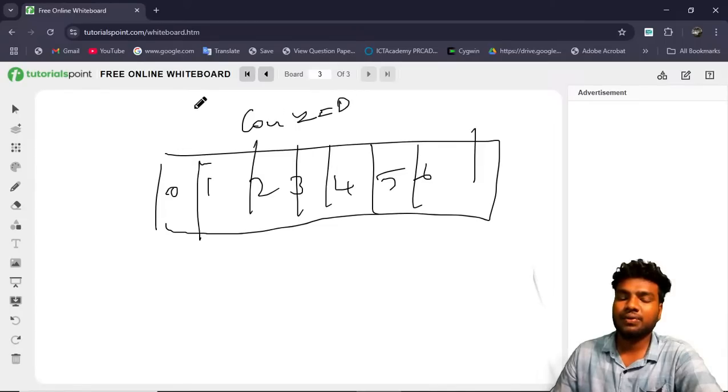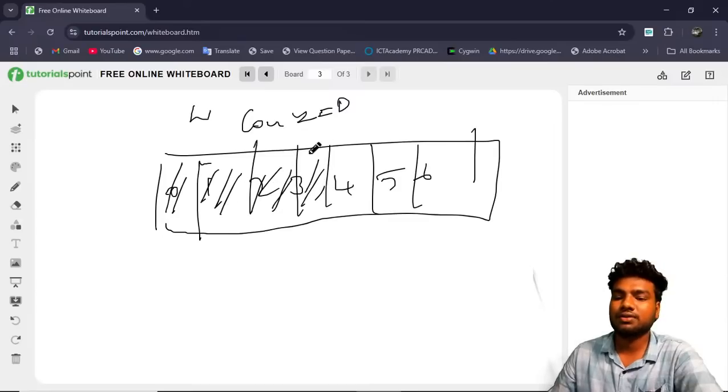If write enable is high, I can write into this memory. I will go next, next, next. I can't go from the 0th to the 5th location using this logic. From today, I will try only sequential writing, which means I will write one by one: first location, second location, third location. It's a sequential location.